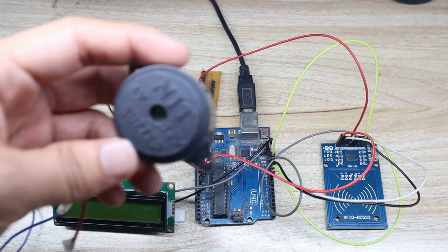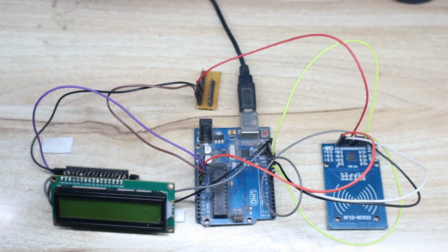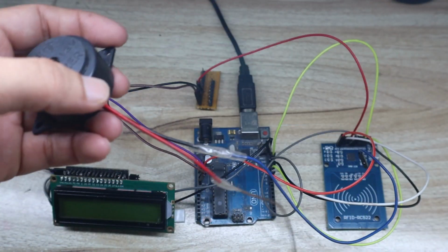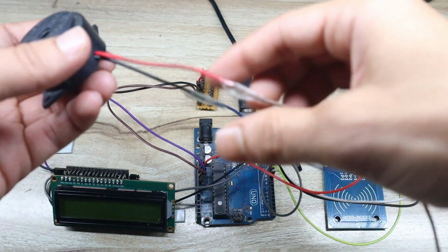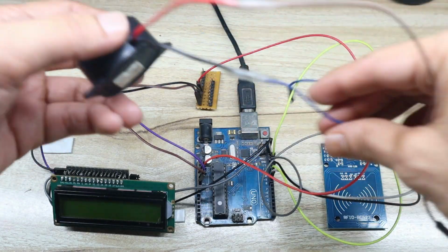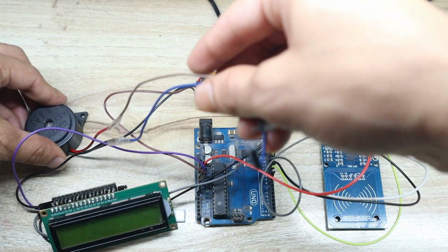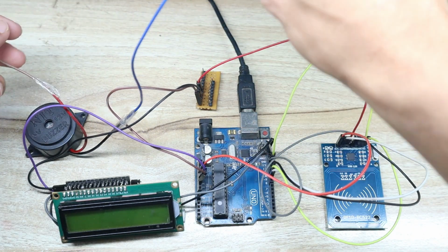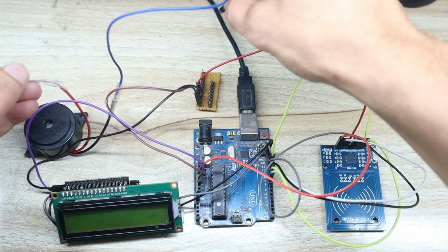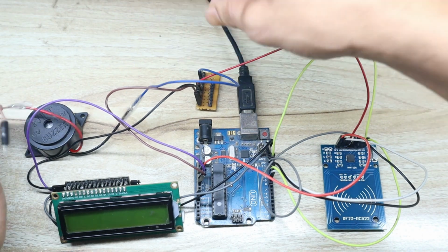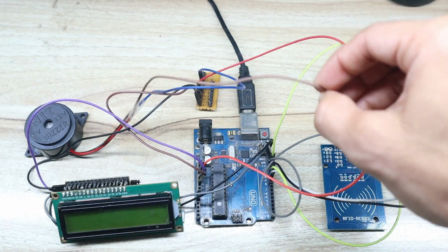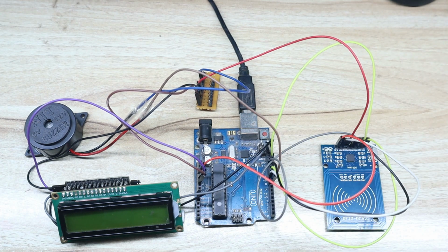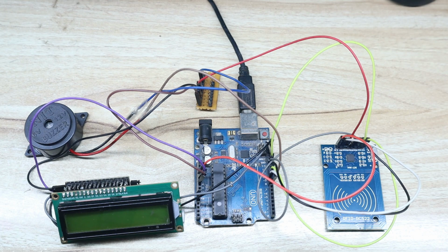Okay, now next hardware is buzzer. So buzzer having 2 pins, very easy. Every buzzer having 2 pins, one ground and one VCC. So just place the buzzer here. So just connect the ground pin from the buzzer, that is the black pin, should be connected to common ground, and the positive pin from this buzzer should be connected to 8 number pin of Arduino. That's it, 2 pins you should connect.